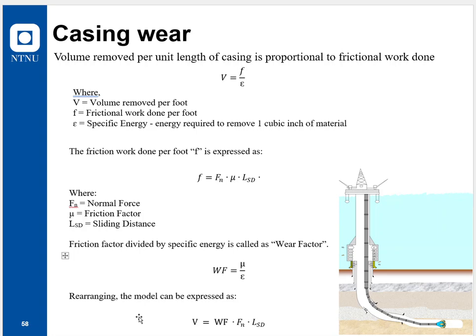We see the side force being extremely important in casing wear, and again I use this drawing with the purpose earlier. Why? Because the highest tension is the most shallow in the well. The highest tension creating the highest normal force in a curvature.